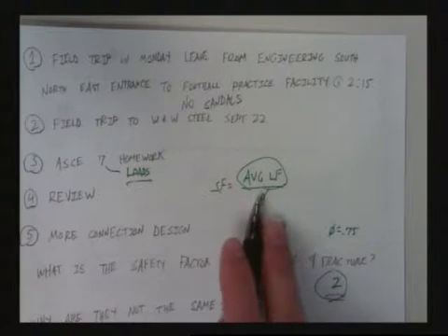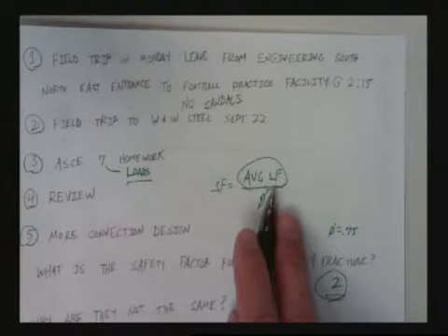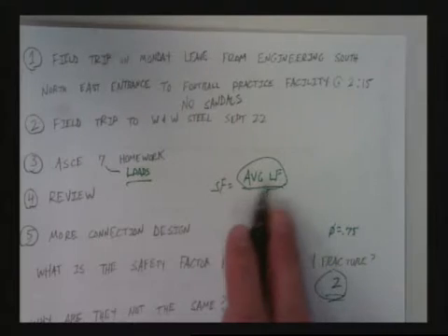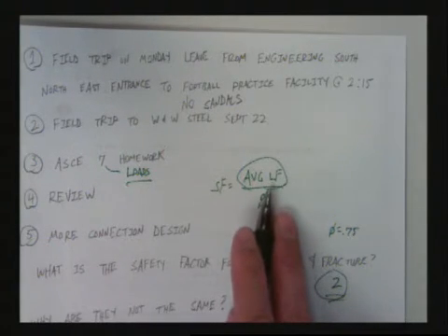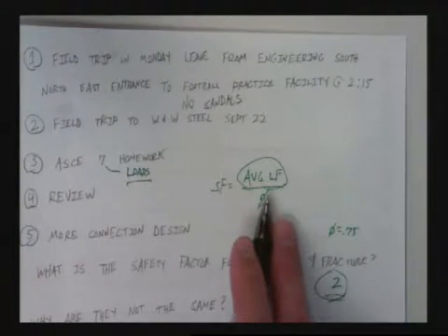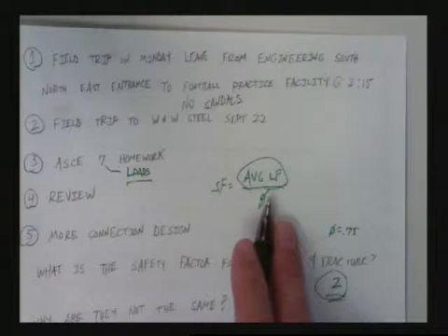Well, if you have more live load, your load factor is going to be more weighted towards the live load, right? The 1.6. If you have more dead load, your load factor is going to be weighted more towards the 1.2. You with me? Okay? And so as we showed in our notes last time, safety factors float in LRFD. They're not constant. And you'll hear people say all the time, oh, I hate LRFD. There's no difference, okay? It's just how the safety factors are applied.